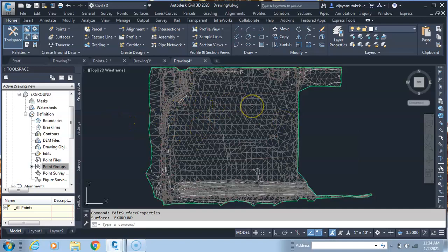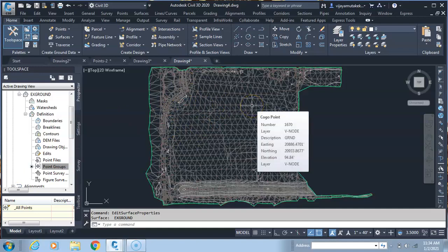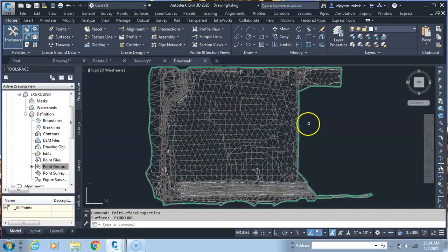So in this way we can create surfaces from the points from the survey data available with maximum accuracy by selecting thin surface. It considers a triangular network, and you can define the logical boundary with the help of the trial and error method or by asking the surveyor about the maximum length. So this is about the surface creation.